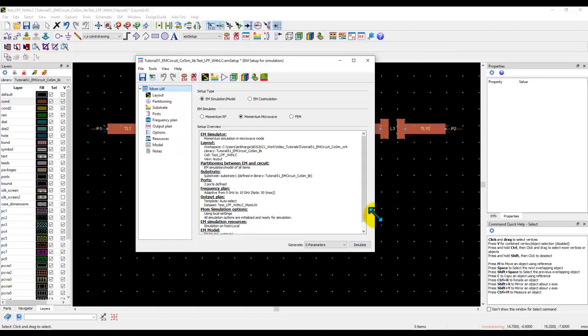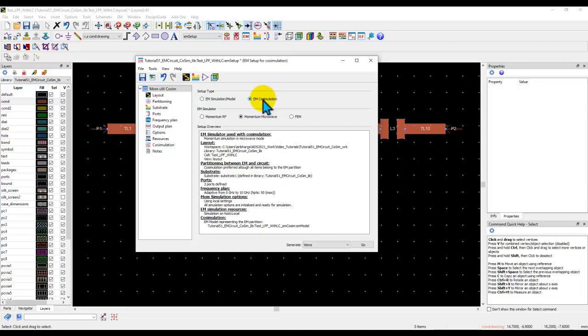So now once I use the co-simulation mode, notice what happens here at the bottom. For EM simulation, it's actually in the simulate mode because it knows it's a self-contained layout and you can go ahead and directly perform simulation. But when I switch it to co-simulation mode, I'm telling ADS or the simulator that I do have some things which may not be simulatable by the EM simulator. Hence, the option here changes to view. That means it will allow me to generate an EM co-simulation view containing all the definitions. All right, so hopefully that is clear.